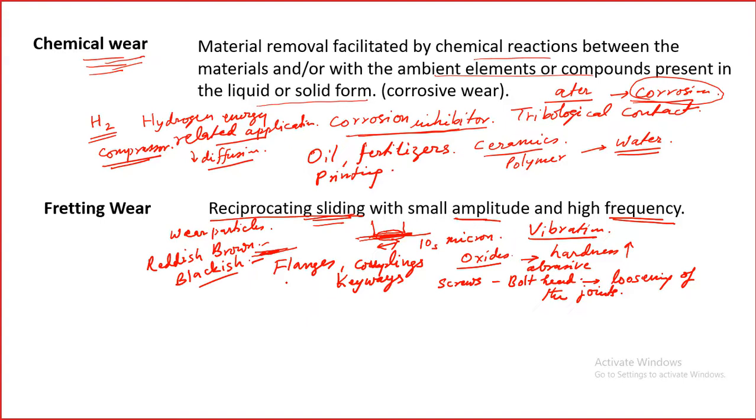In some cases, fretting wear is also known as false brinelling. For example, in some rolling contacts, especially, some minute slip can happen. Because of this slip, the fretting action will happen, and in this case it is also known as false brinelling. So we should know this term, because in industry people use this kind of term to mean basically fretting wear.